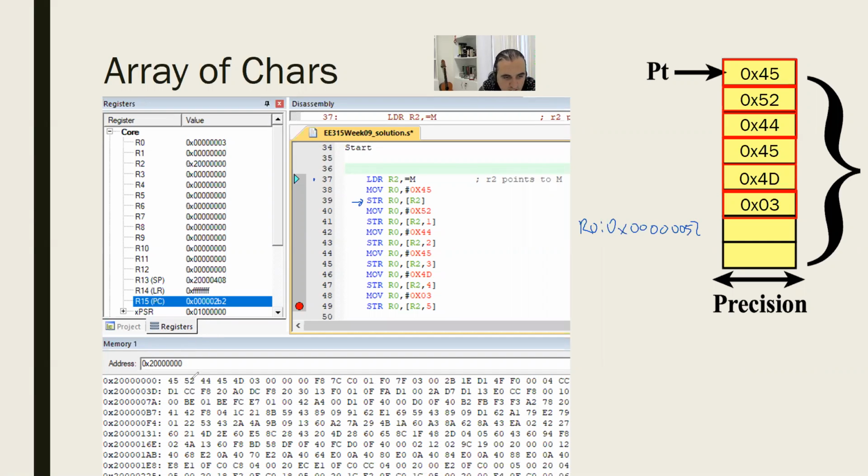It's going to write 52 0 0 0. So that's why it didn't make a difference. But in the end, I had these zeros. I had to write these zeros. If I had used strb, these wouldn't be zeros. They would be the random values which the memory had before I started my instructions. Did everybody get this detail?